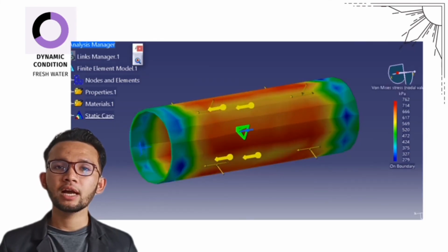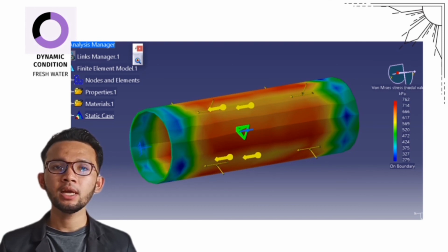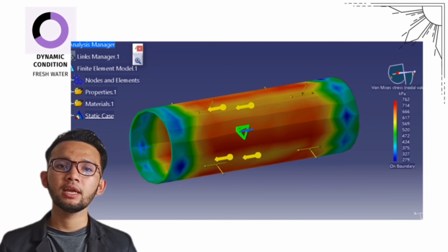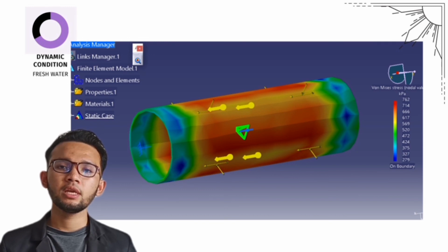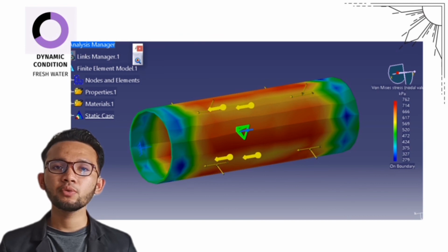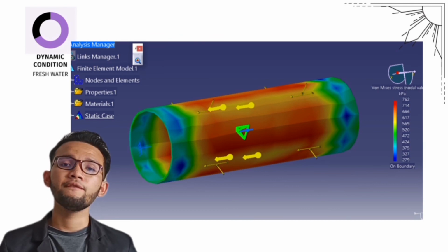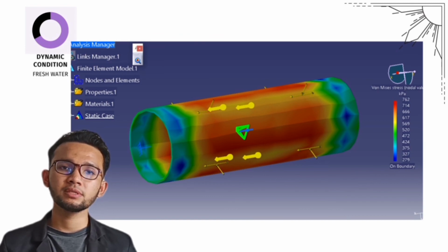a few forces are considered in the analysis, which are the drag force from water, thrust generated by the propeller, and the acceleration of the main body. The value for drag force for the main body is 3.21 Newton, the thrust is 30 Newton, and the acceleration is 66.975 meter per second squared. This acceleration we consider when the body accelerates from 0 until 1 meter per second.